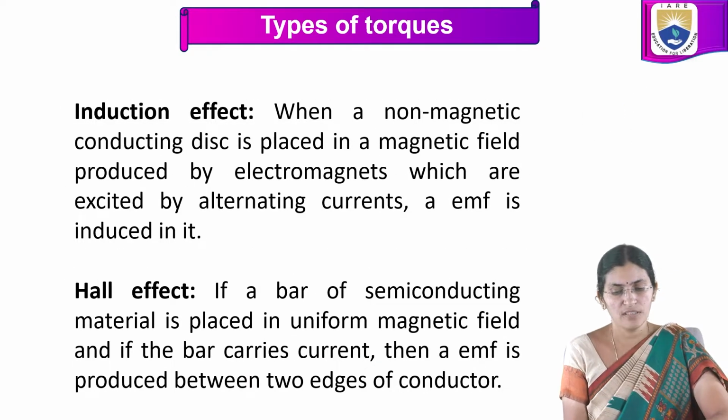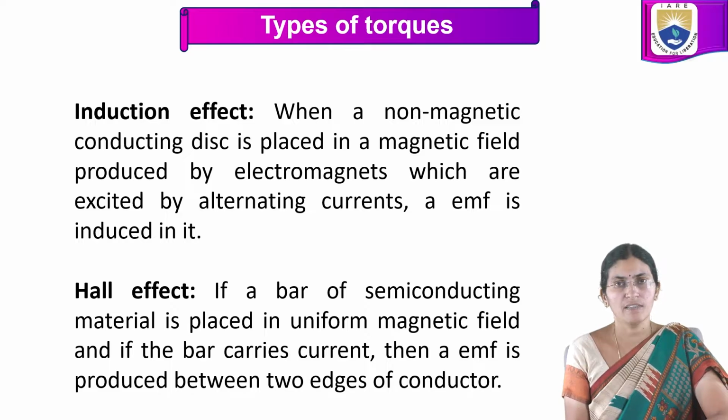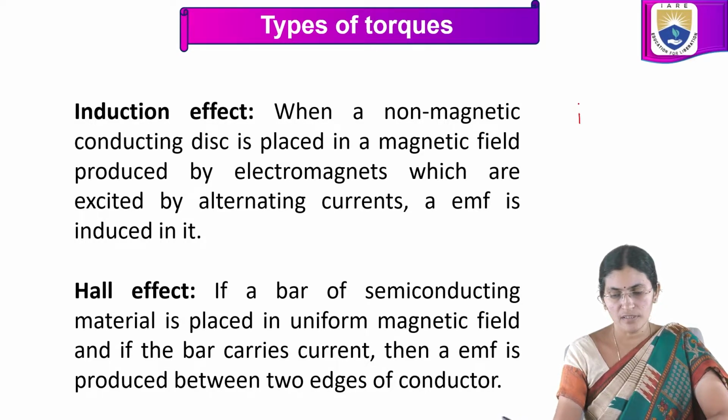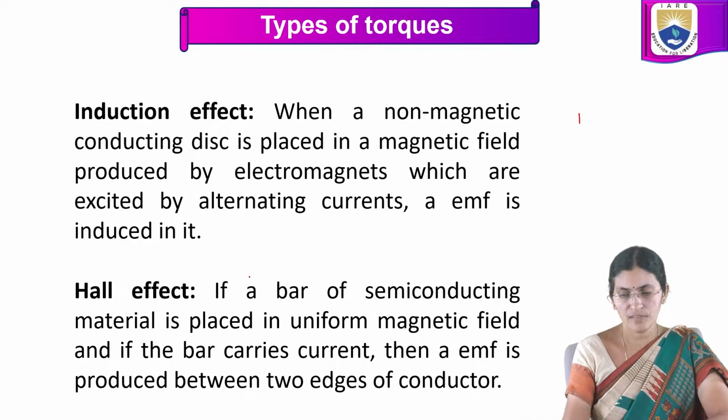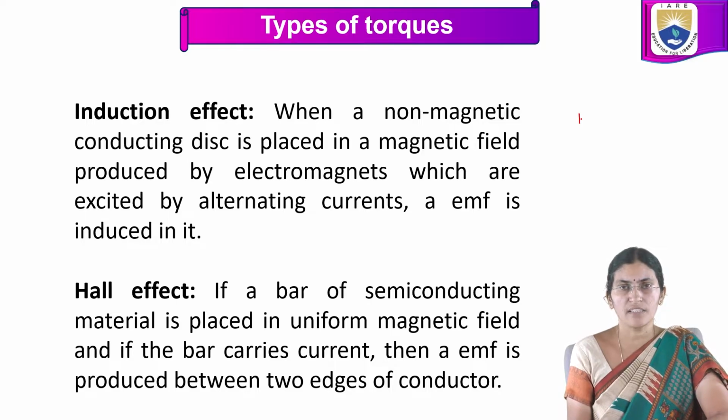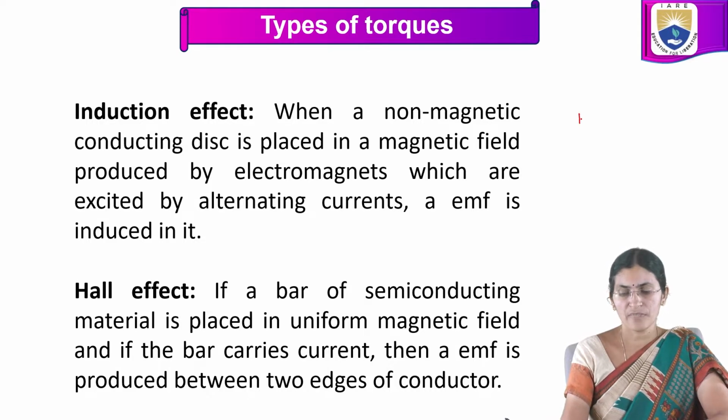Next is induction effect. In induction effect, we have a non-magnetic conducting disc placed in a magnetic field. There will be EMF induced in the conductor, and eddy currents induced in that conducting disc. Due to the interaction of the induced eddy currents and the magnetic field, these eddy currents will oppose the motion of the conductor. So that is induction effect.